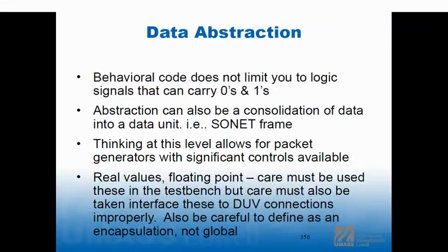I don't think so. What I would rather do, and this can be another level of abstraction, encapsulated over the bus functional model, is say, I want to send a message. I want it to be 1,000 bytes long. I want it to have random data in the payload. I want this to be the destination address, this to be the source address. And that's how I call that task with all of that information. From there, it constructs a message. It calculates a CRC. It might send me an error if I did something that's not legal, if I told it to send something that was too big or something like that. And all this is done within the task.